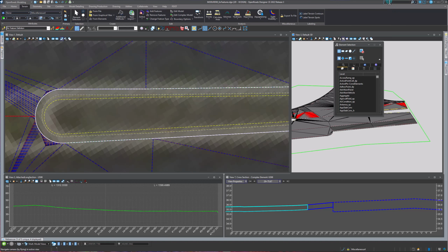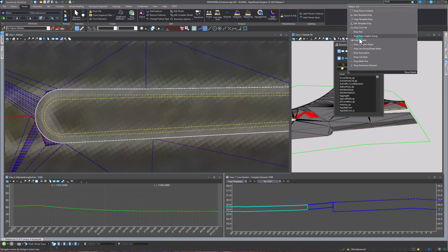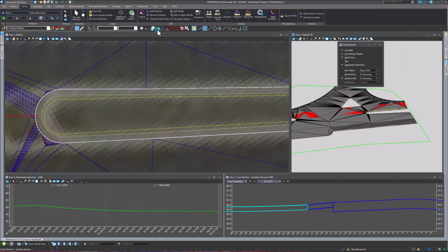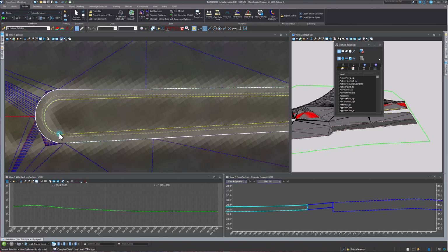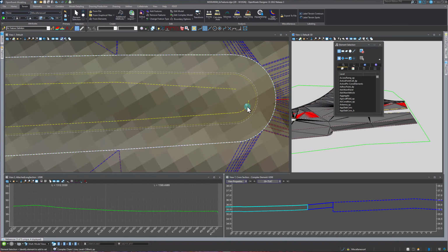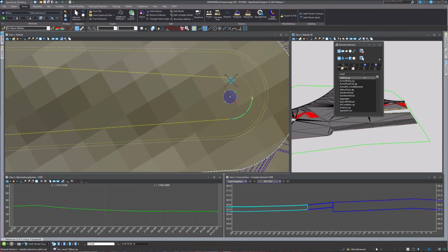Now we're going to go ahead and use that drop tool. Usually I just come up and search here, and you can find that drop element tool. I have it on my toolbar right here that I've created. But what I really want to do is just drop this, and now it's going to be into its lines, and it's not a complex element anymore. We've got some curves here. I'm not really sure why this one isn't closed. It's kind of weird. It should close.